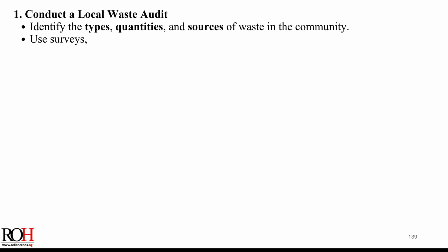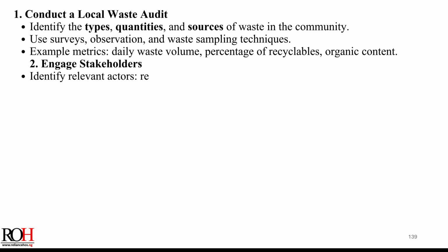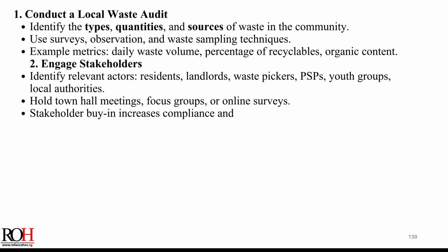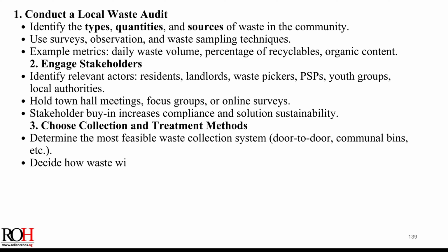1. Conduct a local waste audit. Identify the types, quantities, and sources of waste in the community. Use surveys, observation, and waste sampling techniques. Example metrics: daily waste volume, percentage of recyclables, organic content.